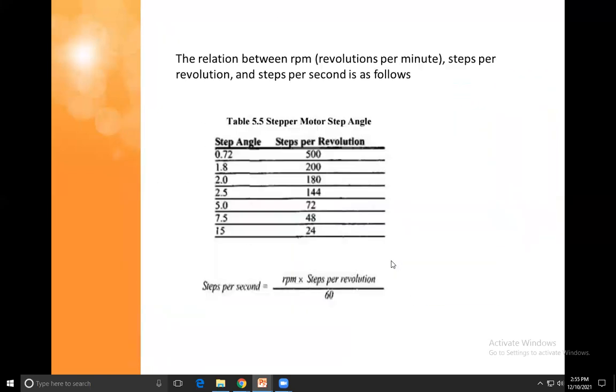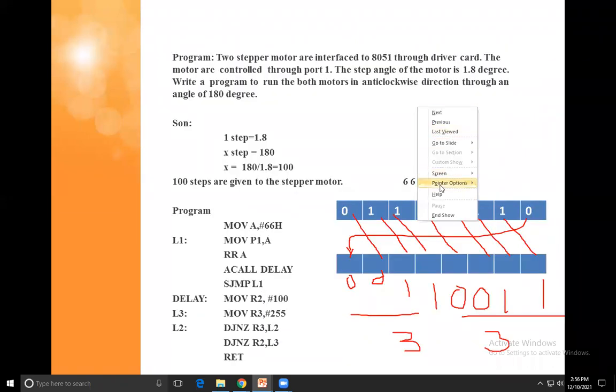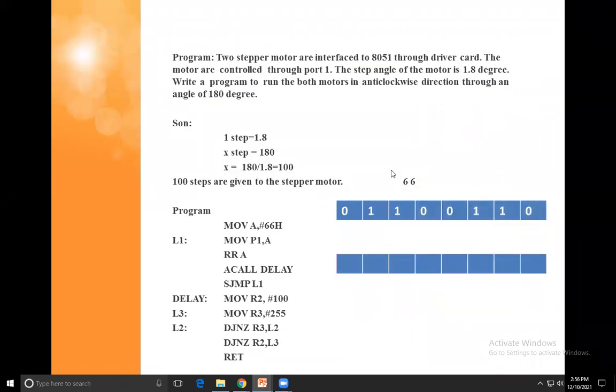Okay. So this is rotate right. In the previous program, a simple program, you had to give the sequence directly to the input of the accumulator, but now you remove those 4 to 5 lines and give only one line, rotate right or rotate left. With one line you rotate the motor to the right or left. Okay, so this is the program for the DC motor.